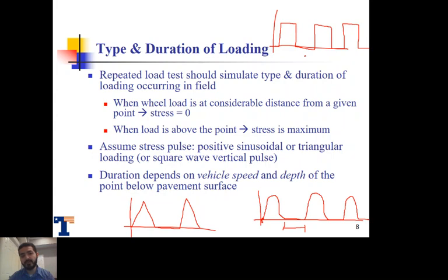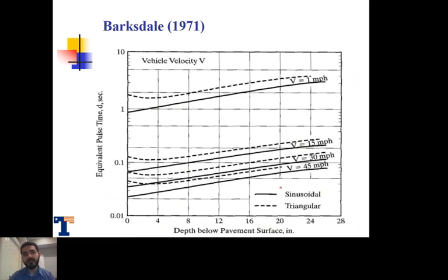The duration period of each one of these loadings actually depends on the vehicle speed as well as the depth of the point of interest below the pavement surface. So you may wonder how long this loading lasts. Again, it depends on the speed. If the vehicle speed is low, therefore the loading will stay applied longer at that specific point. If the speed is high, then the loading time would be very small.